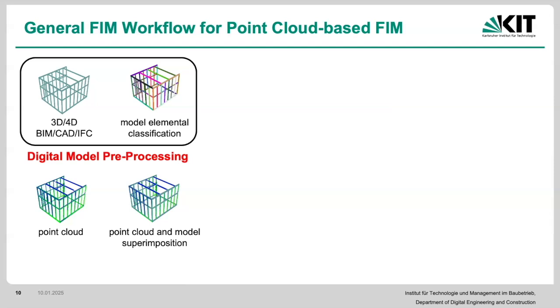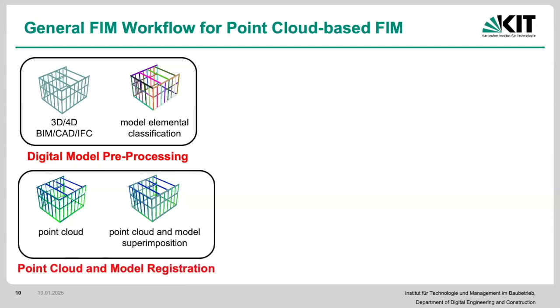Yes, exactly. That's exactly what I'm trying to say. When we have a speculation of error, even a speculation of it is sufficient, right? Because if I want to control the quality of this column, then I can't use this column or the information related to it from the point cloud to do my initial registration, right? So what do I need to do? I need to make sure that I have some pre-surveyed control points, that I know its location, and use those for the registration. Okay, makes sense? And that's basically what we have to do with the superimposition.